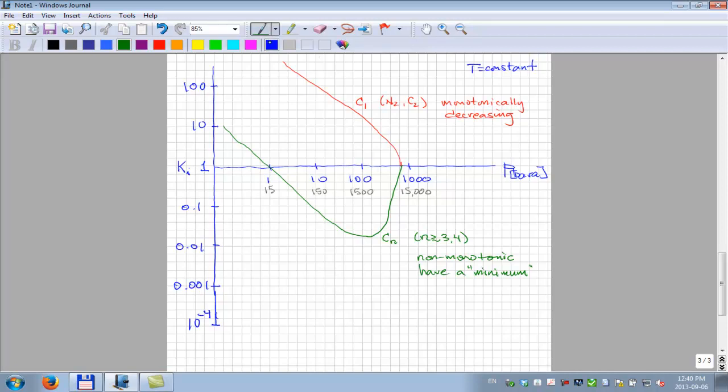Most of the processing that is done, where we have control of the pressures and temperatures in the process, the surface processing, is typically at conditions of this pressure to about this pressure. This is where we do our surface processing. And here we, in a sense, have control of the pressure and temperature. If we put enough money in, we can change the pressure and temperature to try to keep the components in the liquid phase.